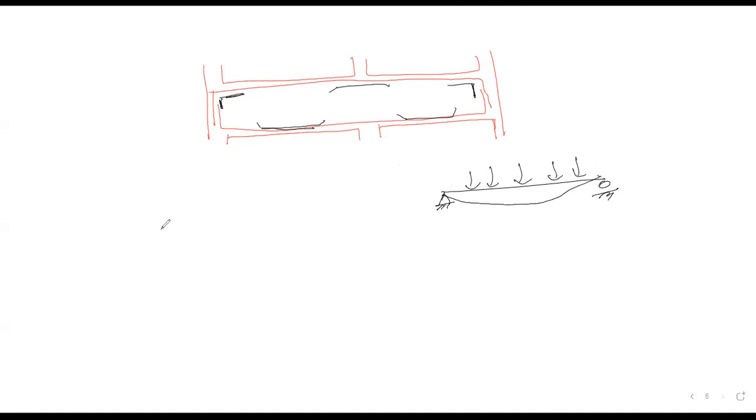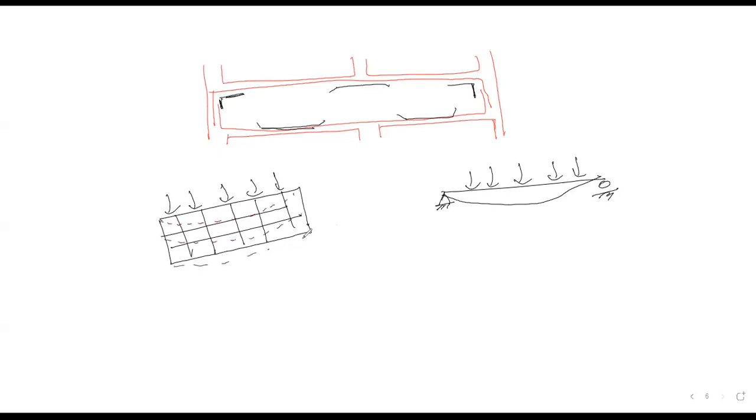Yes or no? Take a sponge, the sponge used in the sofa at your home. Draw a grid on it like this with a sketch pen. Now apply load on that. You people are easily able to see the deformed shape, yes or no? The deformed shape will be easy to visualize. Now in that case we easily see that your topmost fibers, think of the different layers as fibers, are under compression because their length decreases, and the bottom portion's length increases, yes or no? Clearly visualized here, yes or no? So we can say that it is in tension, yes or no?